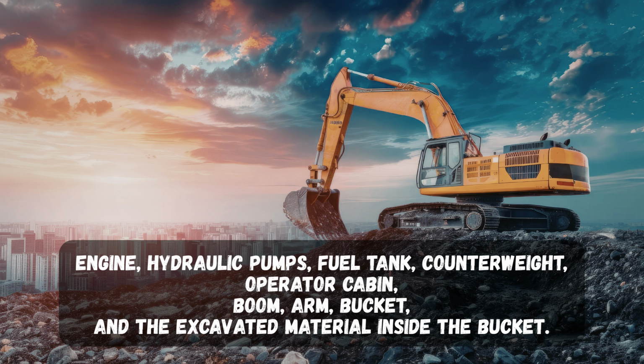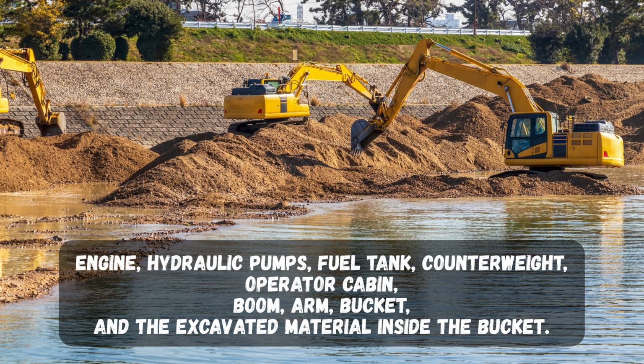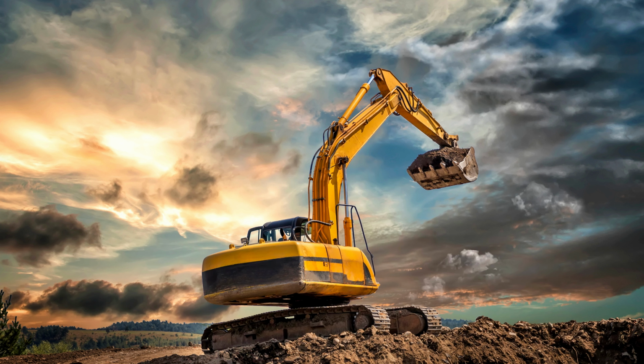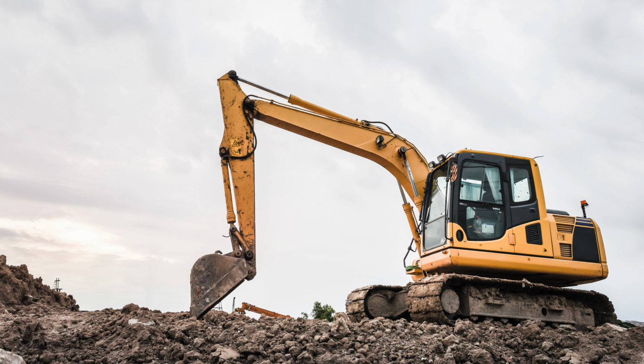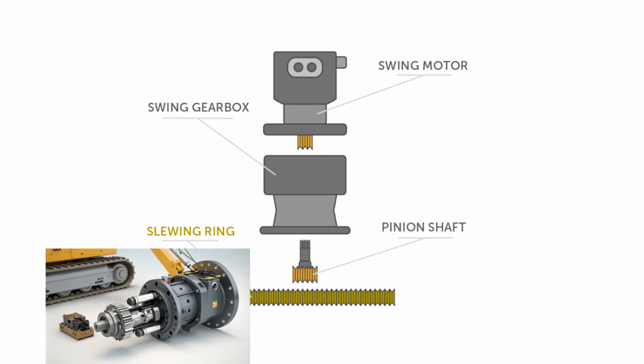The rotating mass includes major components such as the engine, hydraulic pumps, fuel tank, counterweight, operator cabin, boom, arm, bucket, and the excavated material inside the bucket. Because this rotating assembly is extremely heavy, the system possesses significant rotational inertia, meaning that it resists changes in its rotational motion. When the excavator begins to swing, the swing motor must generate sufficient torque to accelerate this large mass. Similarly, when the swing motion needs to stop or change direction, the system must decelerate the rotating mass, which again